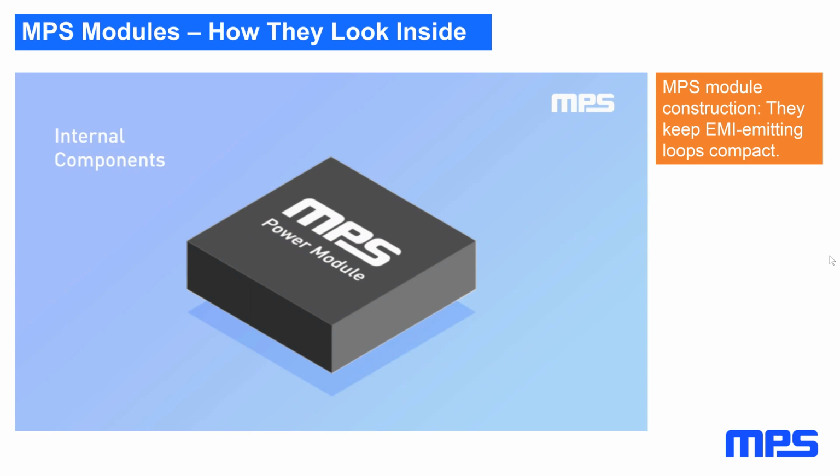The thing is that a module gives you additional layers and is very compact. So the inductor, switch mode regulator, and decoupling capacitors are much closer than you could do on an individual board. And for that reason, they typically perform a lot better on EMI. And we will dwell a little bit into it.